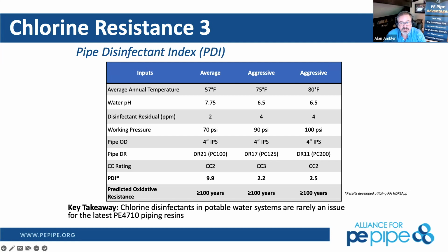And the use of chlorine dioxide as a primary disinfectant also should be looked at. So the difference between primary and secondary disinfectant is the primary disinfectant is at the treatment plant, secondary is within that pipe network. So Matt, you're definitely right on the money. Just wanted to reinforce that one point home. In between that EPA max and minimum, we are good to go.